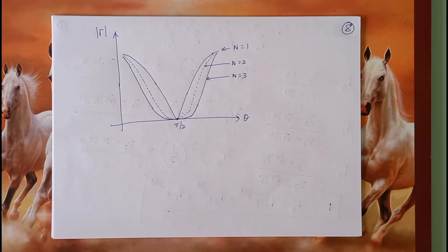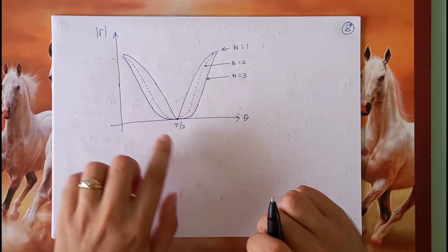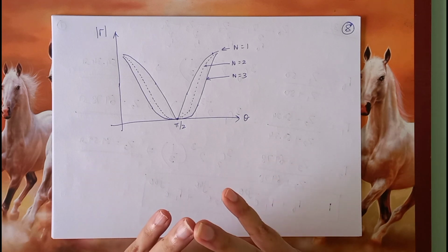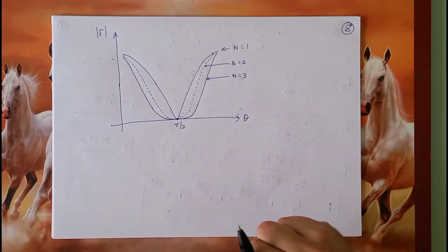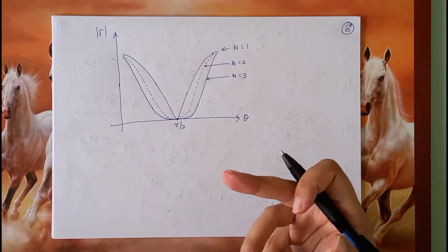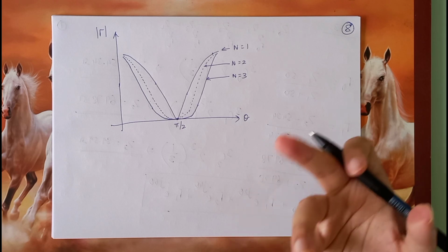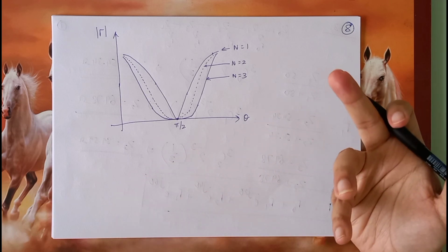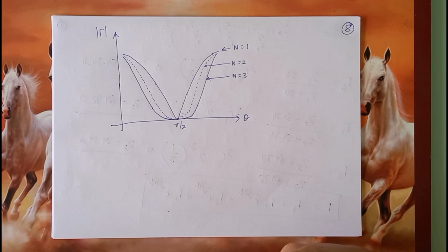It is also called a maximally flat transformer. So therefore, just by changing the individual reflection coefficients, we are able to observe a very significant difference in the frequency response of the impedance transformer, that is mod of gamma versus theta. So there may be some applications where you may need maximally flat responses. There may be applications where ripples are okay. In that case, you have a choice. You can either use the Butterworth transformer as needed, or you can use the equal gamma transformer as needed.